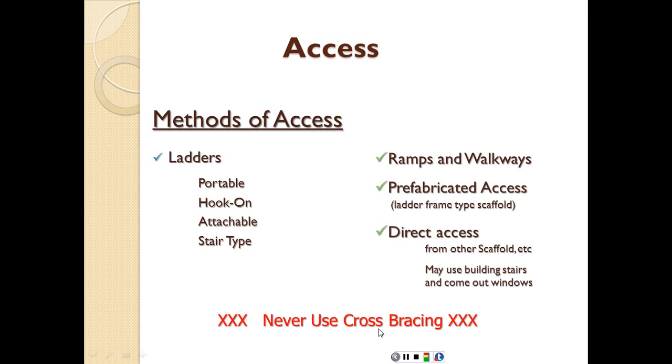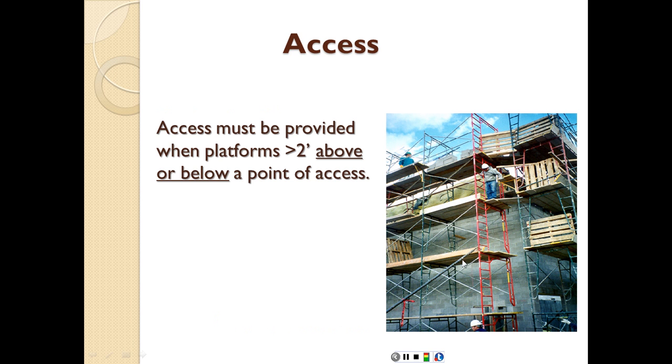Never use cross bracing. This is the cross bracing. Some people would climb on this cross bracing. It's not designed for that, so it may collapse. So never use the cross bracing to access the scaffold.